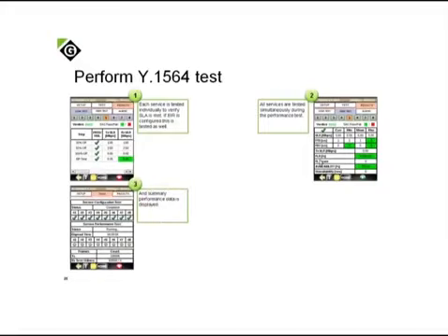Once the test is all done, the system comes back and gives a completed service configuration test and shows the performance data across all of it. Are all these services passing properly? If only one service is working and the other 7 are getting dropped, that's an indication that something isn't configured properly in the substation or the network to carry the traffic flow and all those services simultaneously. We would know if a particular service was failing because it was configured wrong. Here it tells us if the network is configured wrong, because we're able to send all those flows simultaneously.